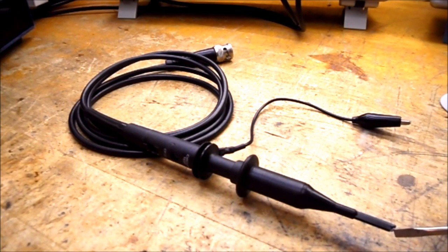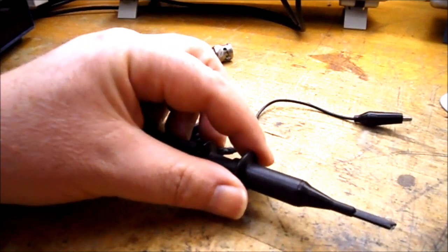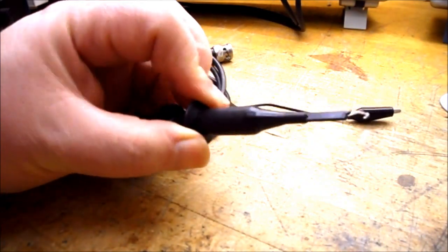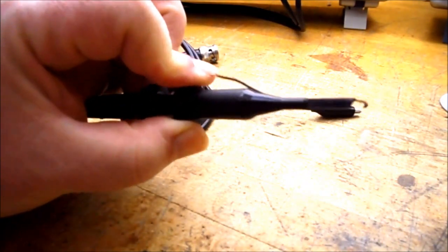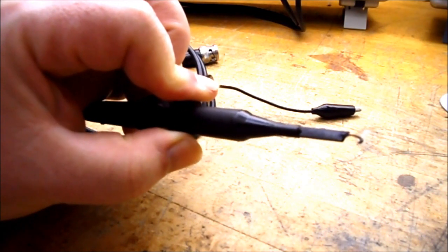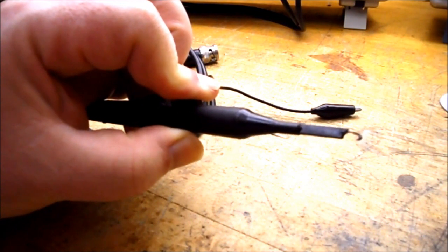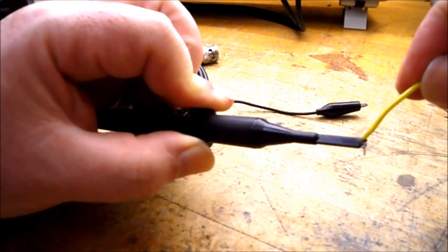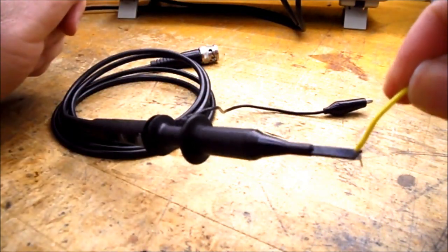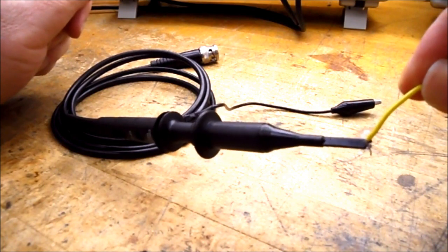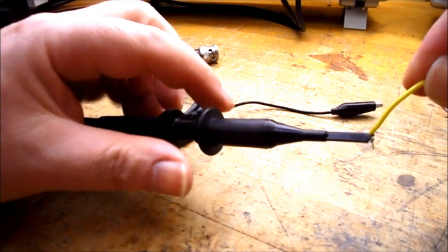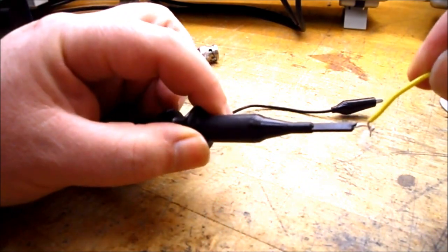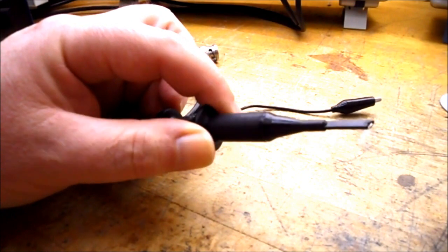On the positive tip of the probe, you can see that we can actually retract it, and it has a little hook in there, so the hook can actually go around pieces of wire or around resistors. So typically it would just clip on there like so and just hang off, and it wouldn't fall off. And to disconnect it, you just retract it again and then take off whatever it's hooked to.